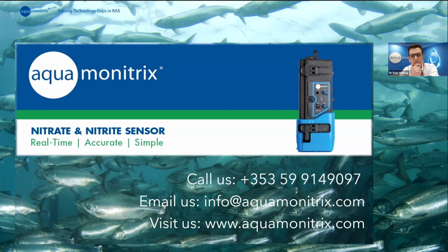We do have other columns available, but typically we're aiming for a guard column because low back pressure is what we're after. And because we have a highly selective patented UV LED based detector, we're not that concerned about interfering species because it's so selective for nitrite and nitrate.